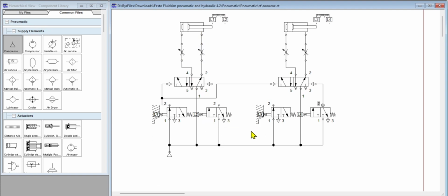Okay, so we have two directional valves, 3-way valves left. In order to release, at the same time this L2 will be pressed by cylinder 1.0 when it is extended. So that means L2 and L3 will be operated together in order to resolve the conflict.